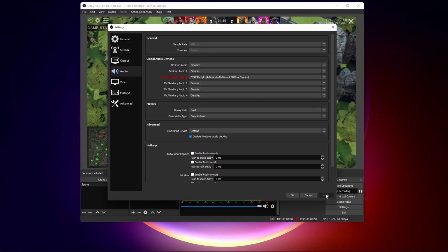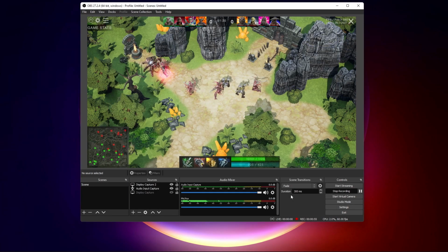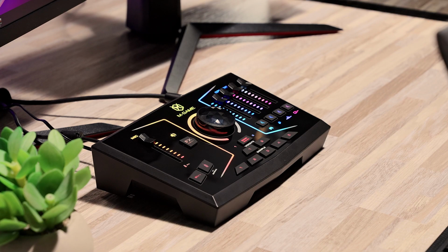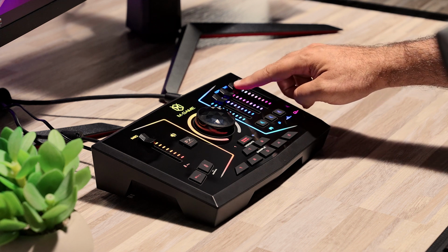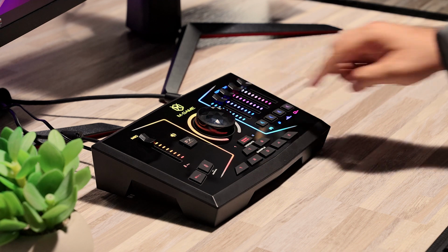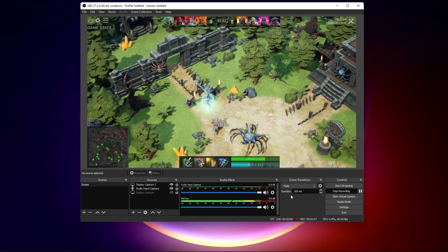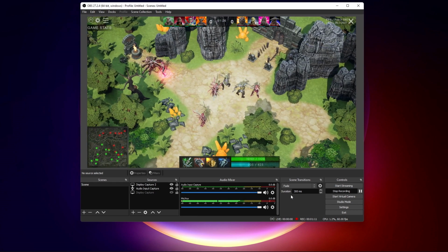Make sure that your full broadcast stream audio is not clipping going into the red in OBS. If it is, dial back the individual hardware faders on the M-Game until the broadcast stream signal from the M-Game is no longer clipping. A signal in OBS between -15 dB and -10 dB should be a good broadcast level.